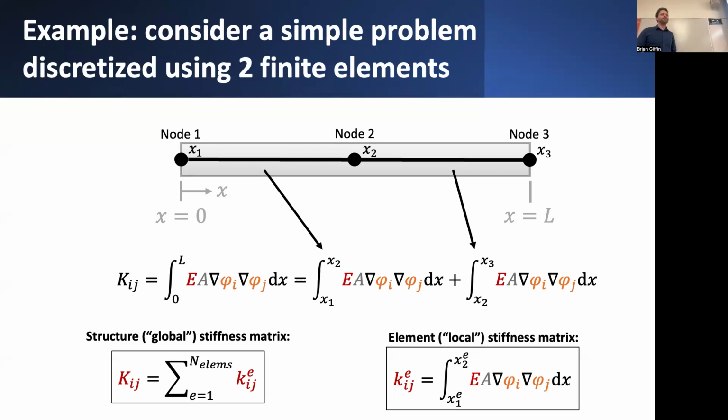So the overall idea here is that if we wanted to compute the stiffness matrix entries for this global system of equations that we're trying to set up and solve for the unknown nodal displacements, we could pose it in this format, or more simply, we can say assemble, or sum up, all the different contributions to this integral from each individual element, and pattern them together in the appropriate sub-indices of this resulting array. And you can interpret that process as being basically just this statement.